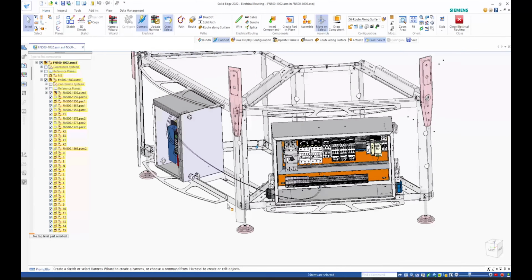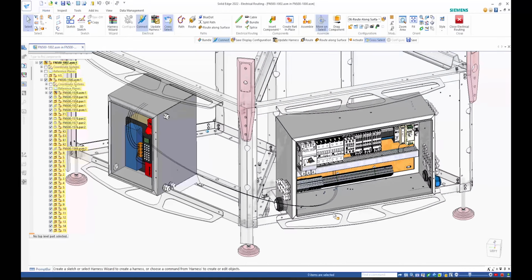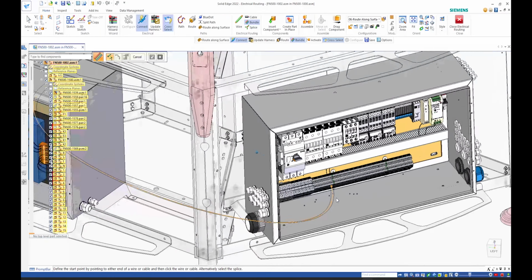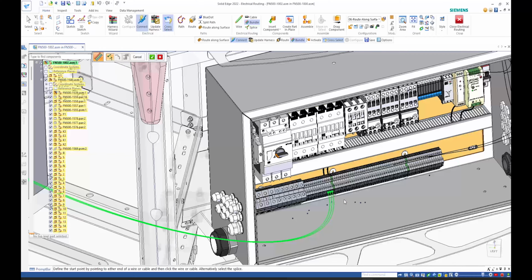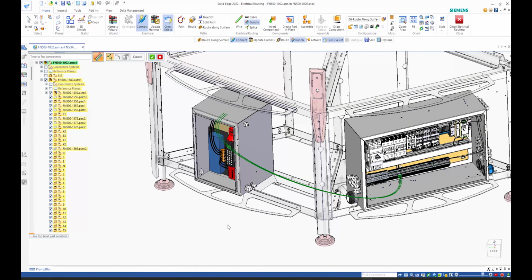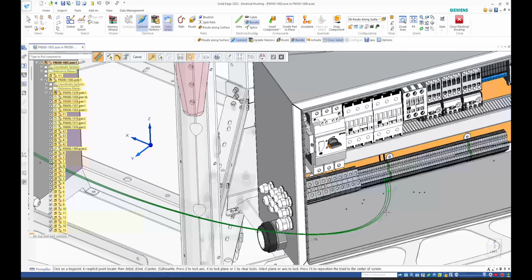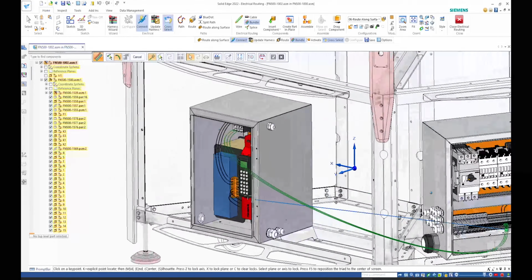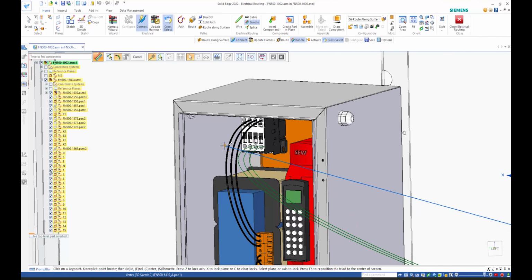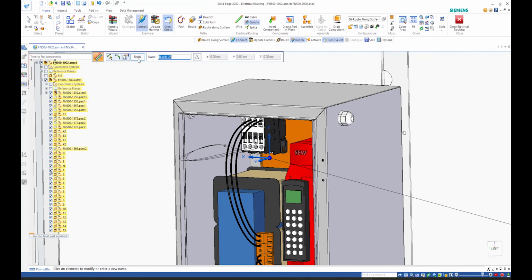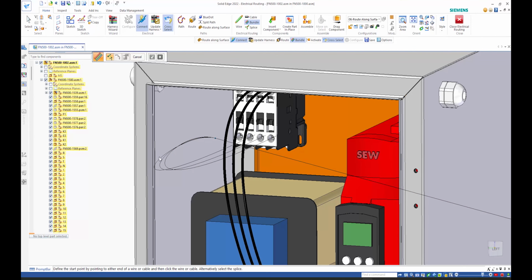The next thing to do is to create a bundle. So I'll select the wires here and accept that. Next, I'm going to create a path on the fly. I use this tool right here to predefine a point, from this point to this other point here, and accept that and say yes, preview, finish. And you see how I put the wires; see how they went around to there.